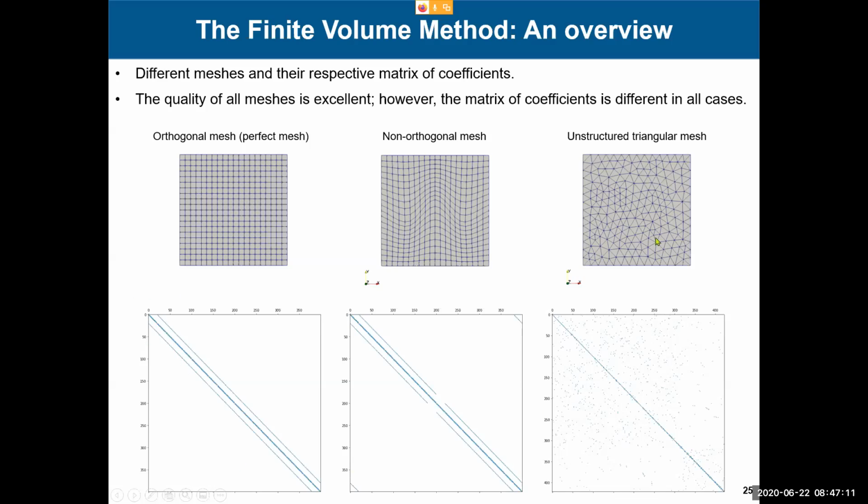So you have this linear solver, and see that as you add some non-orthogonality, your matrices become sparse, and it might happen that one of these elements can become very, very large, and it will make your convergence very slow, okay? So this is what the actual linear solver sees.